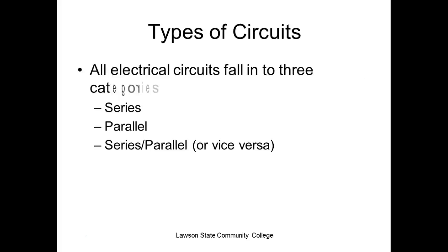So these are our type circuits. Some of y'all are familiar with the first one. It's called a series circuit. Y'all play around with a single element series circuit. In intro and DC, you get into all of it. But we can connect the load. By the way, a series parallel circuit is how you connect the loads, not how you connect the control devices. You understand the difference? So it's how the loads are connected.